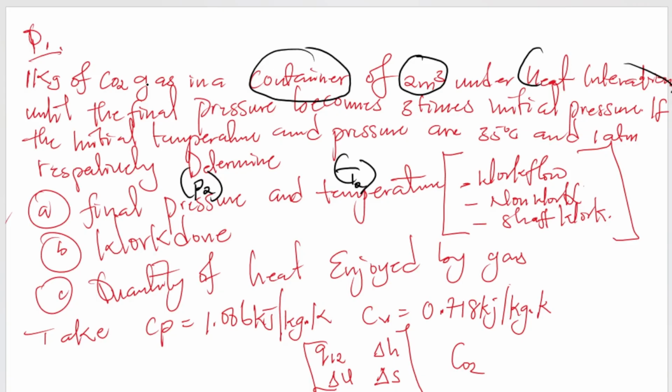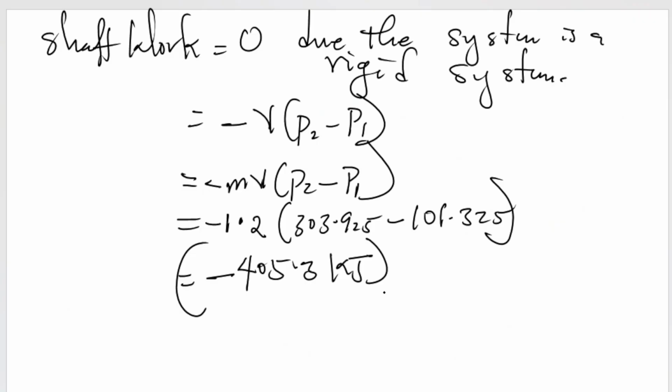8.314. So what you do is you get the gas constant for CO2. Now how do you calculate the gas constant for CO2? Remember, the gas constant R of CO2 will be gotten with the equation Ru, the general gas constant, divided by the molar mass of CO2. Are we together? So first thing first is to get the molar mass for your given gas.